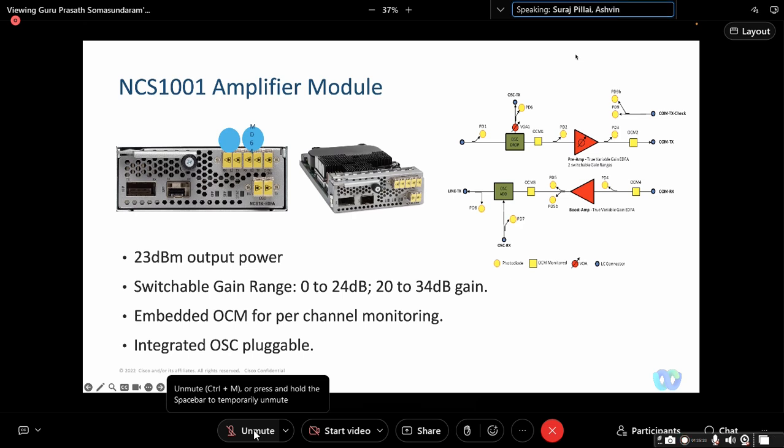That is true, I totally agree. It is very dependent on the circuit. If the circuit is going to be too fluctuating and the span loss is going to be too fluctuating, you can configure manual mode and set the gain yourself. So both are available, and we can do it however we want. But if there is a continuous change in span, you need to make sure that you are recalculating the gain and redoing the configuration every time there is a span change if you are using manual mode. So it is very much left to the operator to decide if they want to change it.